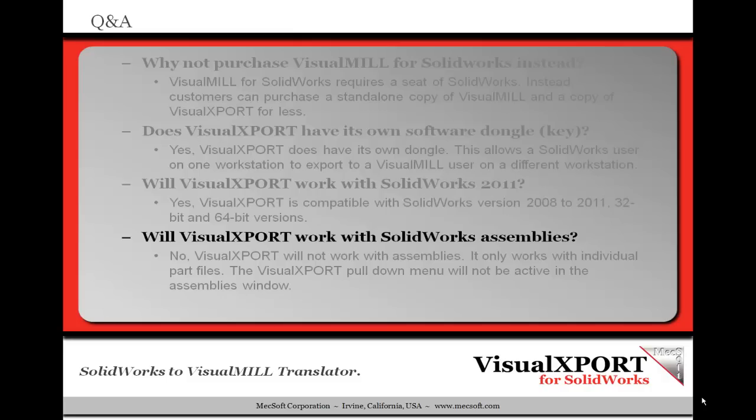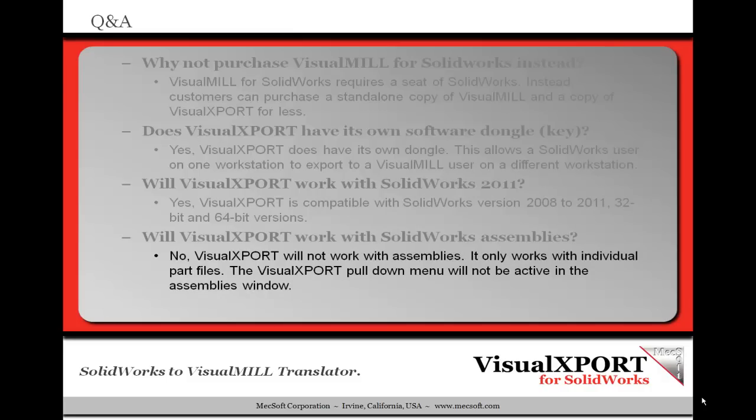Will VisualXPORT work with SolidWorks assemblies? No, at the present time, VisualXPORT will not work with assemblies. It only works with individual part files. So if you are in the assembly window within SolidWorks, the VisualXPORT pull-down menu will not even be active.